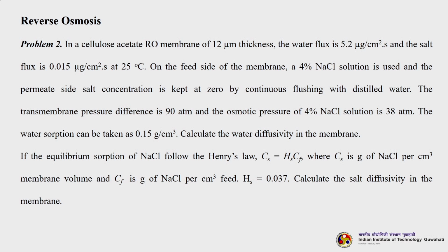So, this is what is being asked. Some data is given that if the equilibrium solution of sodium chloride follows Henry's law, then the Cs is given by this equation, Hs into Cf, where Cs is gram of sodium chloride per centimeter cube of membrane volume and Cf is gram of sodium chloride per centimeter cube of feed. Hs, the Henry's constant, is given as 0.037. So, you have to calculate the water diffusivity as well as the salt diffusivity. Let us see how you will do it.